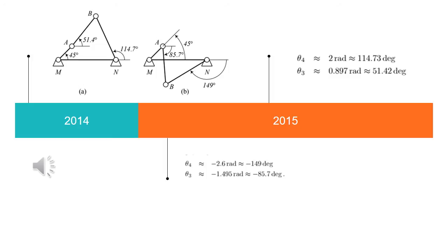And now we can see the figure that depicts the two possible configurations of the linkage for angle 2 always 45 degrees. The configuration in the first figure is called convex, uncrossed, or elbow up, and the configuration in the second figure is called concave, crossed, or elbow down.